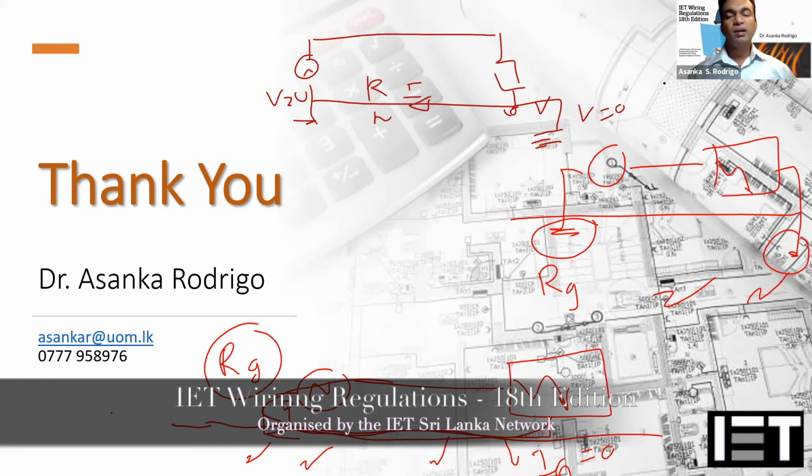As I said, when you compare TT earthing and TN earthing, and you are getting a bulk supply, we get the best protection and the best coordination, everything, in the TN system compared to the TT system. The only advantage in the TT system is the low cost of your earth connection and your circuit protective conductors, because you need a very small size of protective conductor. Other than that, my judgment is TT is not a very good earthing arrangement, and the best is the TN earthing arrangement.